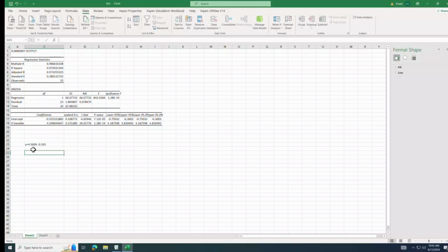And we can see that 4.5 is equal to 1 over tau, which means that tau itself, the time constant, is equal to 1 over 4.509, which is equal to 0.221 seconds. And time constant is equal to what? As you know, it's equal to RC, the resistance multiplied by the capacitance.